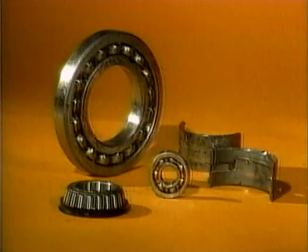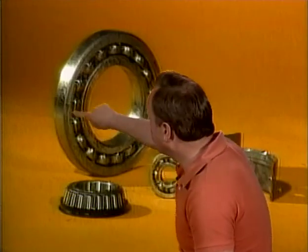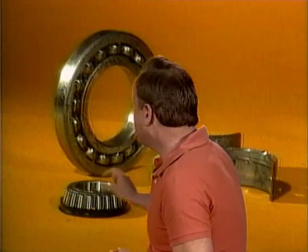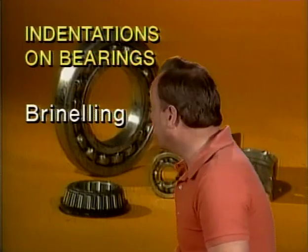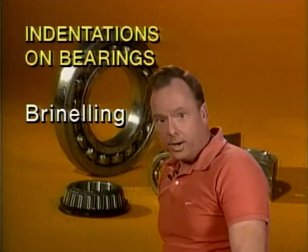All right, let's talk about bearings. When you as a mechanic are inspecting bearings, what are you looking for? One of the things you're looking for on ball bearings is flaking or pitting of the races, little pieces of metal coming out or little indentations of the races. They also ask you, if you have indentations on the bearings themselves caused by high static load, what would that be called? The answer is brinelling, B-R-I-N-E-L-L-I-N-G. That is not a word I use a lot, but that's what indentations on bearings from static loads are called. Now they're going to ask you, how do you tell when you have a failed or failing bearing?